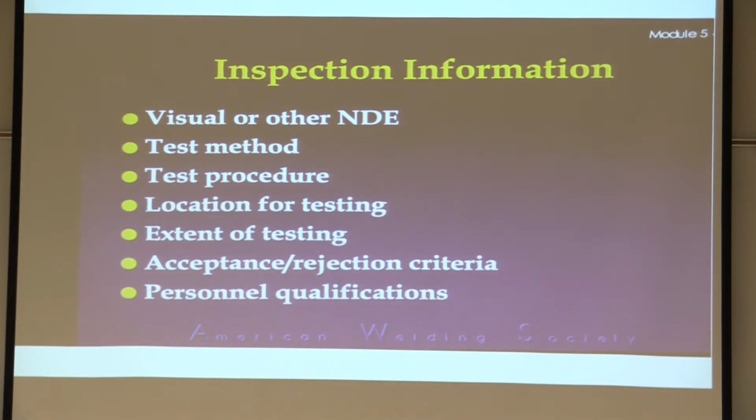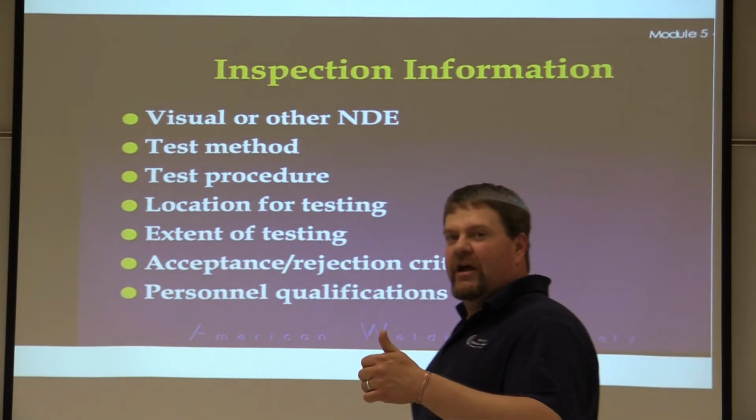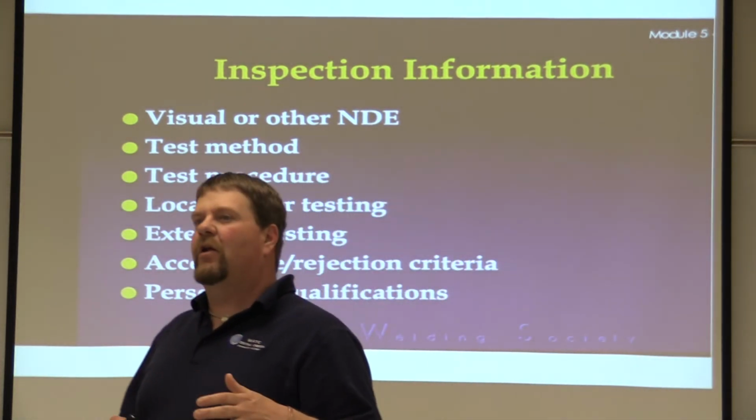All right, we're going to talk the next piece. 5-4, right-hand column. I want to talk about the second part, the second paragraph in there. Before welding, the inspector should review welding procedures to ensure that all combinations of material, thickness, process, position are adequately covered. Also, what type of welding electrodes, what preheat, all those other things.